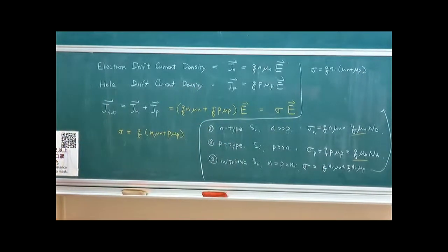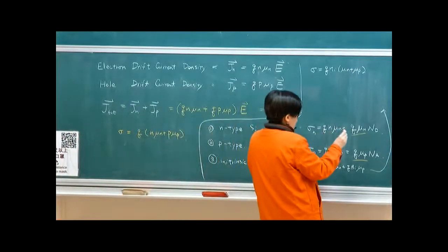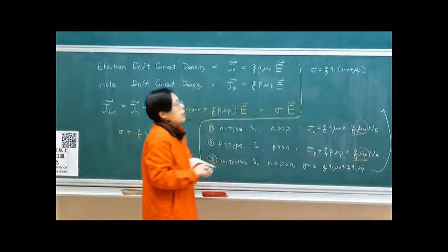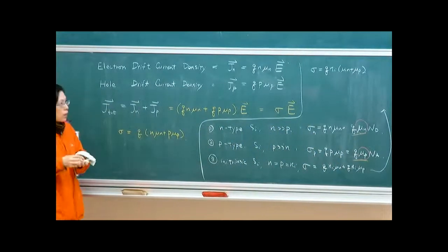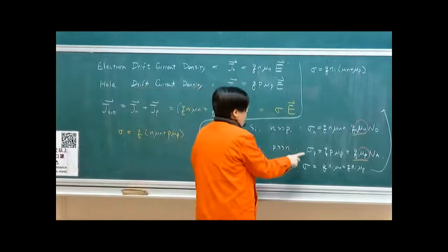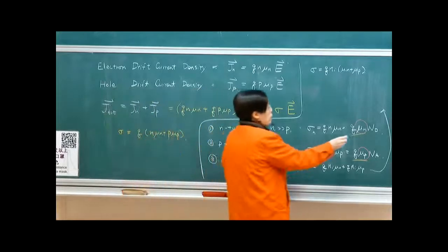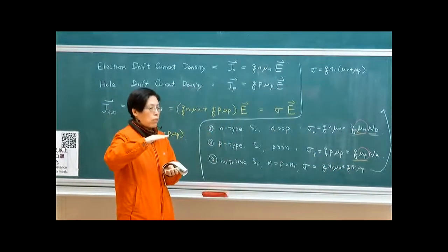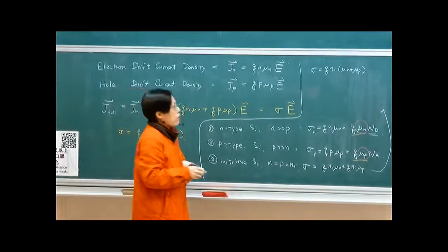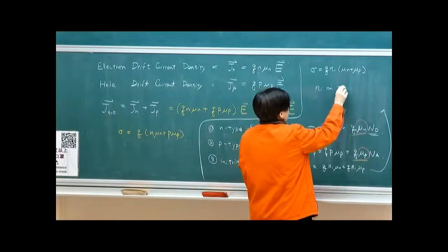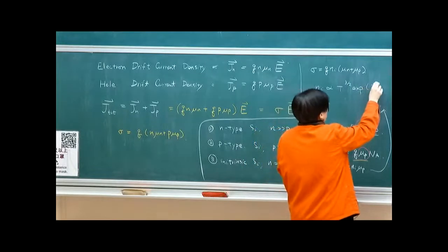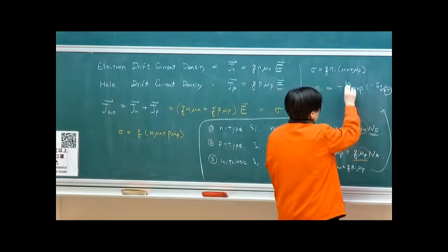So in all these three types of semiconductor, which one is most sensitive to temperature? What do you think? In most of these cases, as I said, there's a slight temperature dependence on mobility. If we ignore that, your conductivity mostly depends on carrier concentration. In these two types of material, your carrier concentration is fixed. Whatever amount I put in will dominate my carrier concentration, so it remains relatively stable. As we already said, your ni strongly depends on T to the 3/2 and an exponential term. I don't think I had the equation right, but there's a very, very strong temperature dependency.